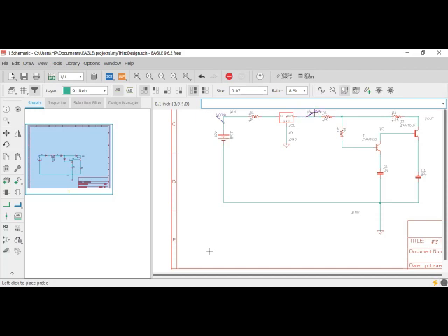We have the voltage of VA. That is the voltage here. Let's add another probe here, which is the VQ. Adding a voltage probe is very important for simulations so that we will be able to get the value for V. And let's add a voltage probe here, which is V out. Then you save it. Hope you are following the steps.